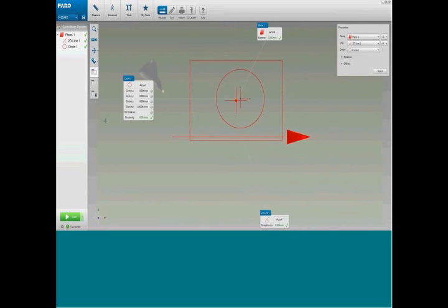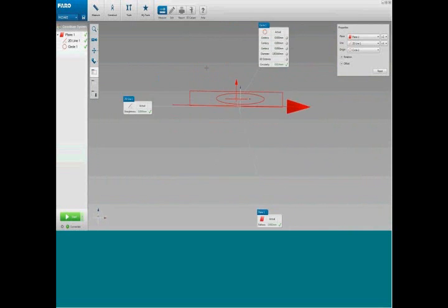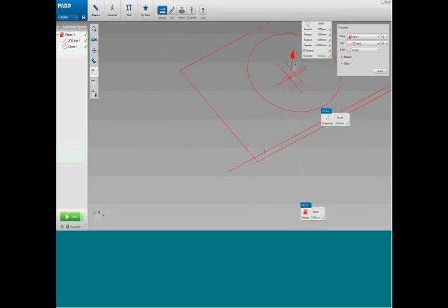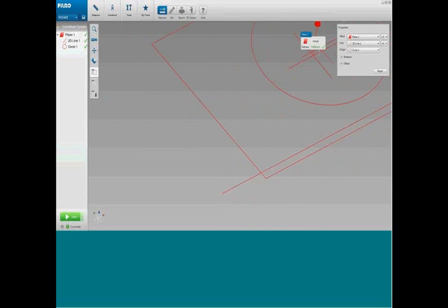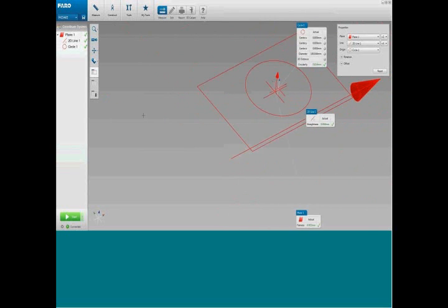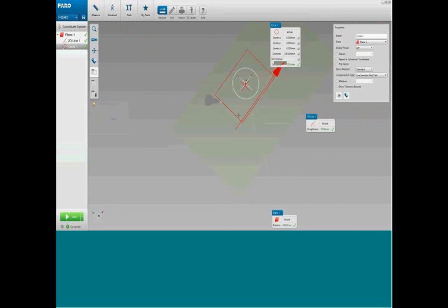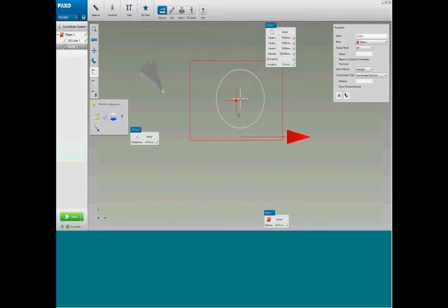If you want to rotate back to a 3D view, hold the left mouse button, and we simply rotate. Right mouse button will allow us to pan. I is a shortcut key in. O, shortcut key out. And again, selecting the feature will automatically rotate to the plane that feature is on. Okay, so SmartInspect adds a new dimension to measurement by actually prompting the user what to do next. I'll be using the workflow suggestions several times during the demo to show how easy the workflow becomes.